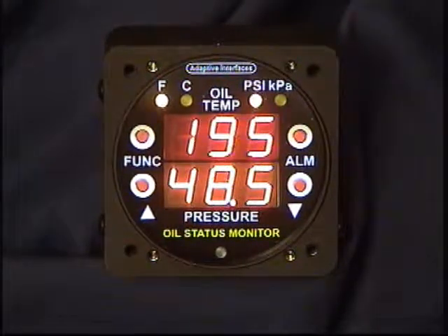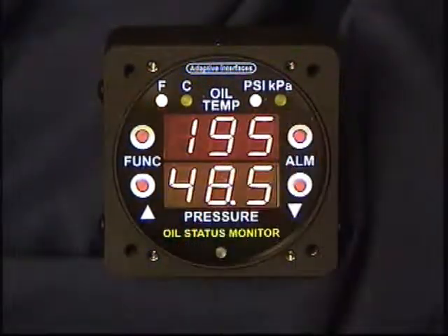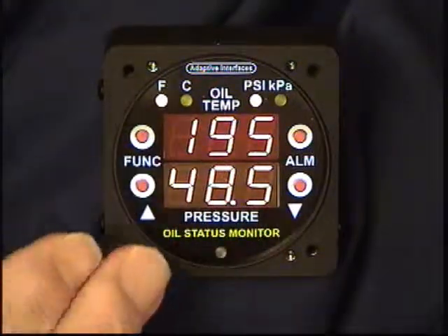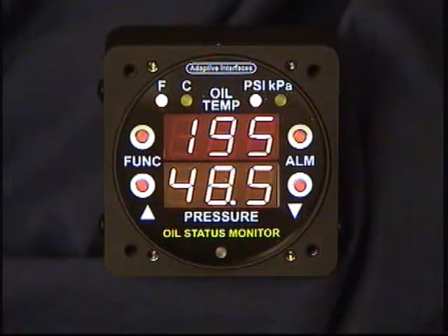Now is when the alarm button on the front of the instrument comes into play. If we want to turn off the alarm condition, we can press the alarm button as such. The instrument goes back to its normal mode of operation, and a 2-minute timer is again started, and if the alarm condition still exists after 2 minutes, it will go back to flashing and be in an alarm condition. If the alarm condition goes away, the instrument will continue to operate in a normal operating mode. If the alarm condition still exists, you can continually press the alarm button to turn off the alarm and work on the problem as you're flying.